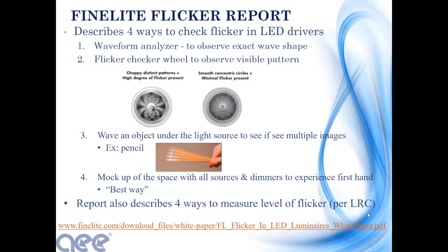But you can use that to observe the visible pattern. If you see a choppy, distinct pattern, that means there's a high degree of flicker present. If you see, on the other hand, the photo on the right, you get smooth concentric circles, and that means there's minimal flicker present.